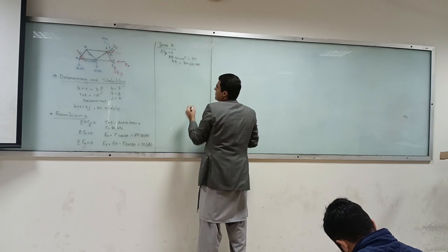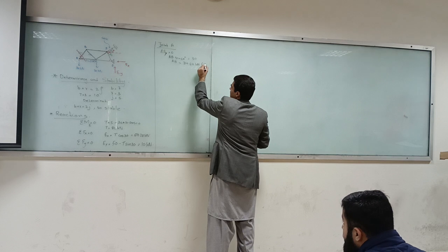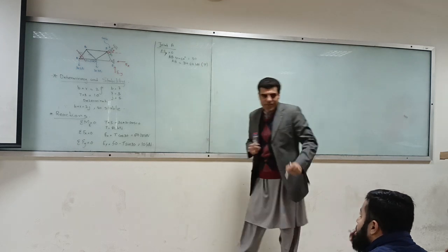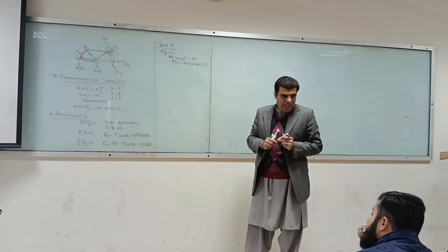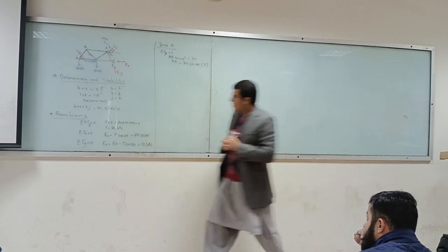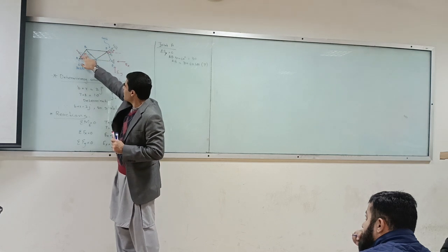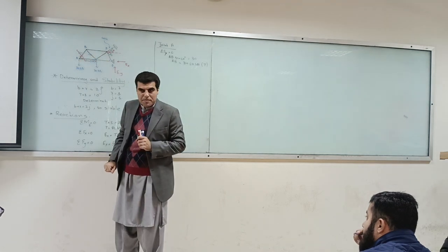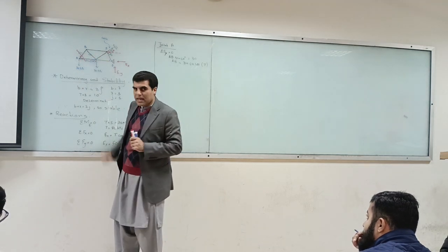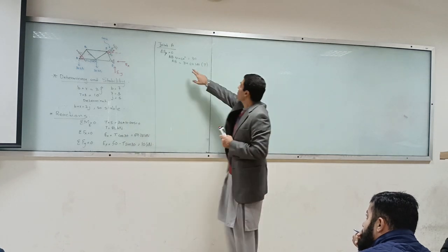If it is positive, that means it is in tension. Let's use common sense to see whether we really get tension or not. What do you think? Yes, sir. Because we are pulling it in this direction, obviously this and this will be in tension. This one will be in compression.